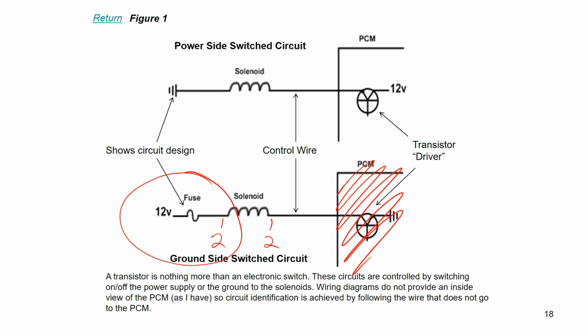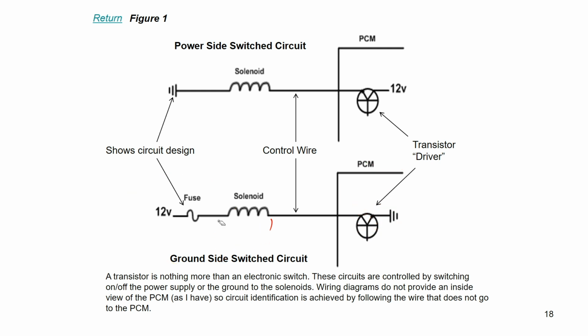What if the driver was stuck on then? Good question. If my driver was stuck on, and this will be stuff that the more you see this, those numbers will be burned in your mind on what a normal circuit would be. So we said, I should have done this, it's my fault I didn't: 12 and 12 with the circuit off.